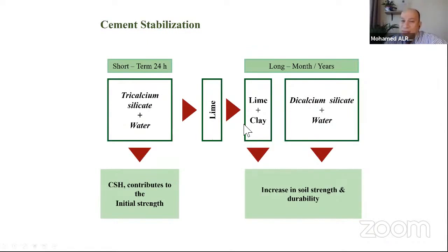And there is some lime lifted from the first reaction, and this lime goes in a cycle with the clay minerals, generating the pozzolanic reaction again, which again helps to increase the soil strength and durability.